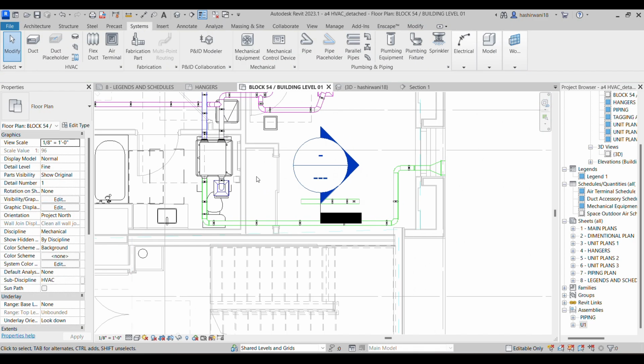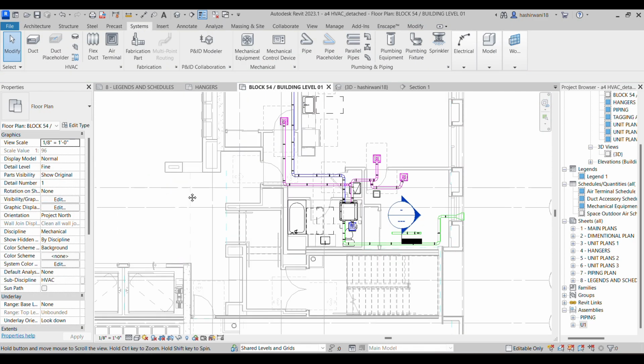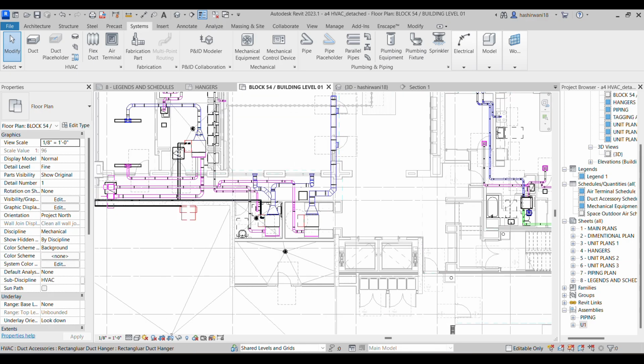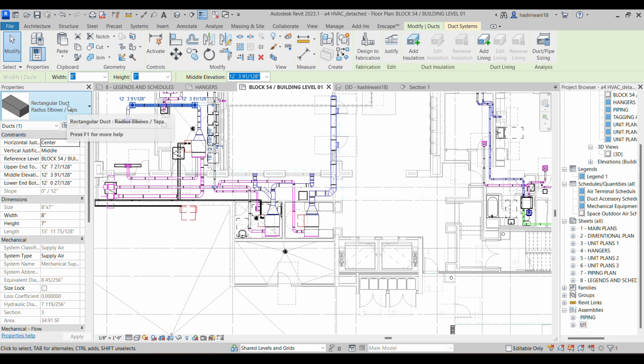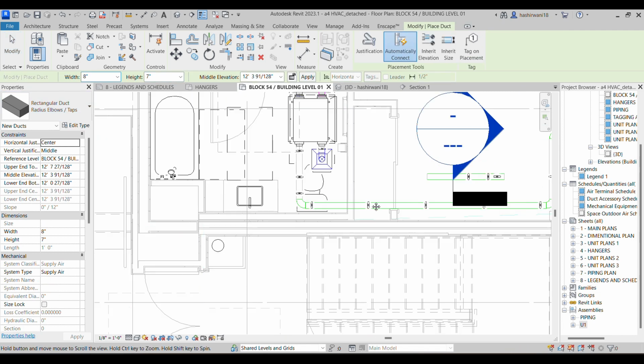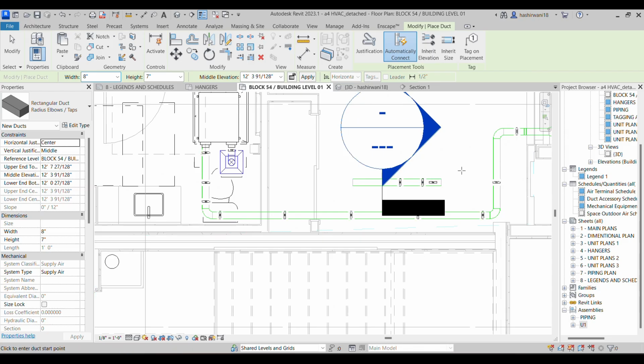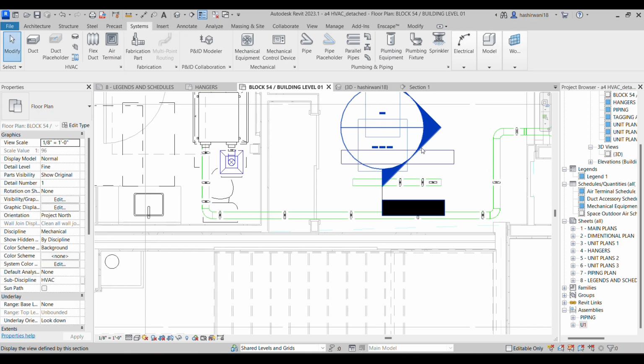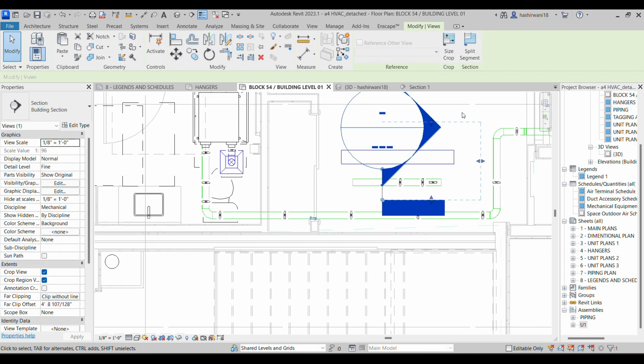So now let's move on to some rectangular hangers here. For that I'll go here and I will select a rectangular duct. Is this a rectangular duct? Yes, it is. I'll select CS, which is create similar. I'll move on to where my section is, simply go here and place this rectangular duct. I'll simply extend the view of this particular section. I'll go here, it has been extended.